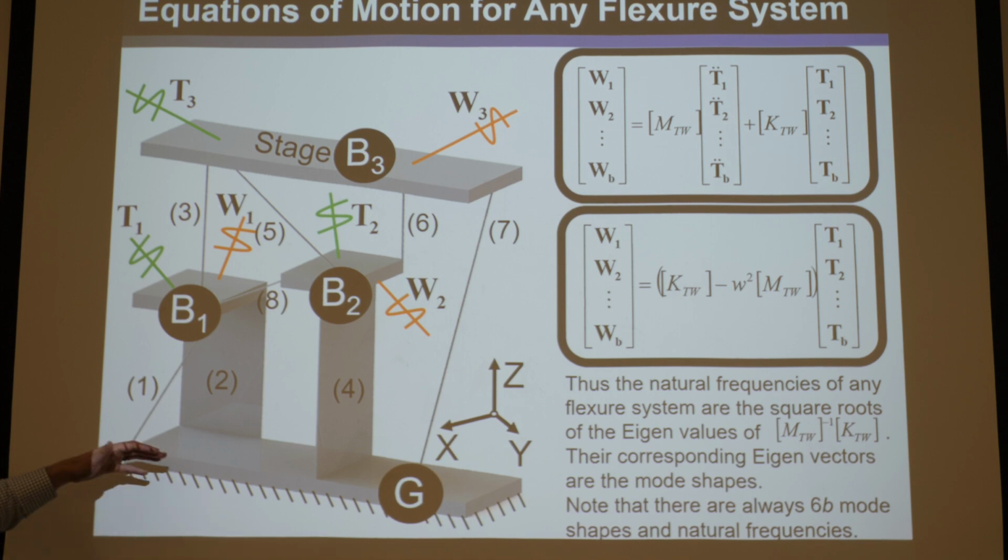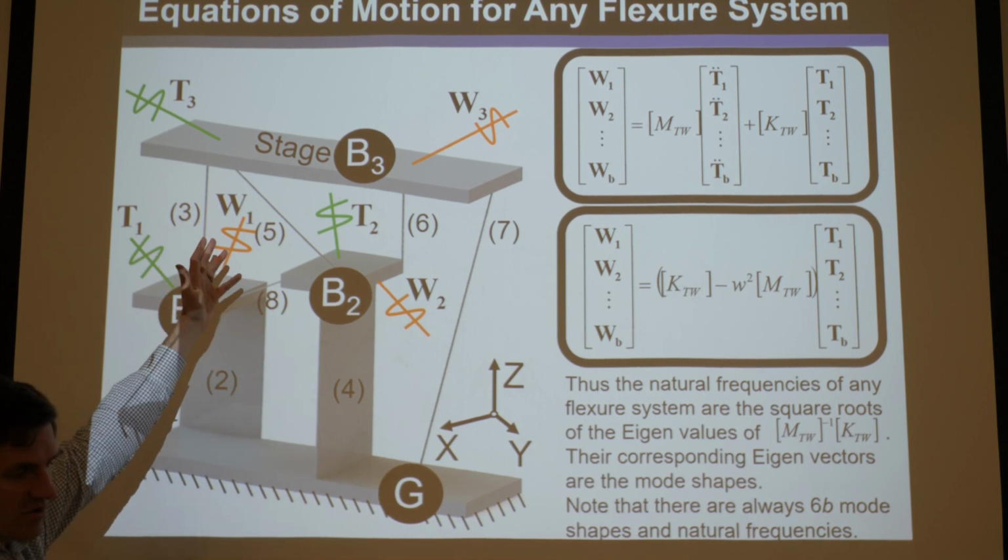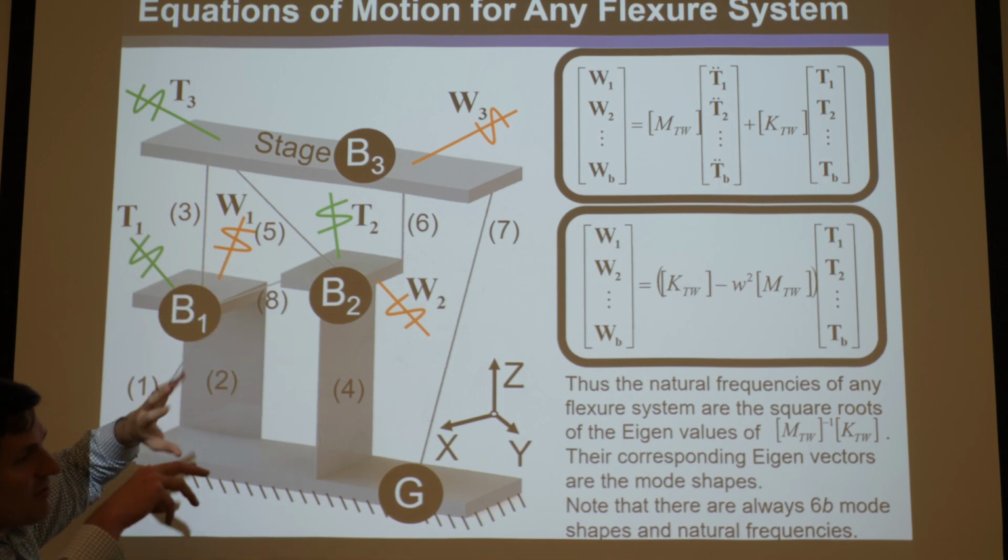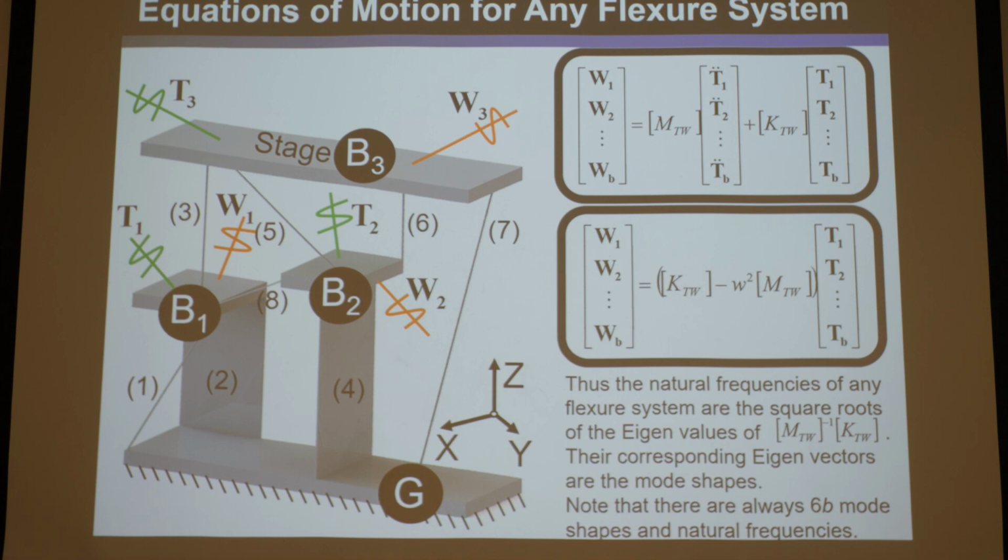So if you could model this as trillions and trillions of atom masses joined together by little atomic bond springs, then you'd get a giant trillion by trillion, something huge, mass matrix and stiffness matrix, and that would produce that many natural frequencies and mode shapes. So that explains why, in reality, things aren't modeled as having lumped masses and lumped compliance. Everything has some compliance and some mass, and it's all distributed. And so as a consequence, it has infinite natural frequencies and infinite mode shapes.